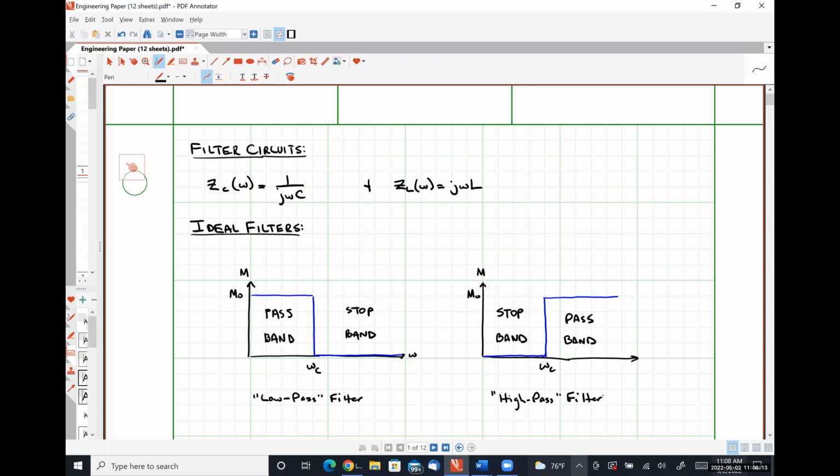All right, so before we address the next two types of filters, I want to talk about these here very briefly. Okay. Low pass filters and high pass filters can be recognized as first order filters. What I mean specifically by a first order filter is that they only contain a single energy storage element. So we can realize both of these filters with a simple RL circuit or a simple RC circuit, and we can get both responses out of both combinations. Okay. We'll talk about how to do that briefly.